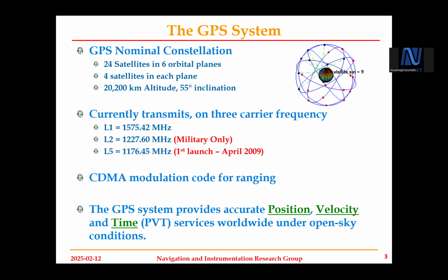And since all satellites use the same frequency as we discussed before, distinguishing these satellites becomes another challenge. The GPS system operates in the L-band frequency using the code division multiple access, or CDMA, modulation technique. In this technique, each satellite is assigned a unique code to identify that satellite by the receivers, since they share the frequency band.